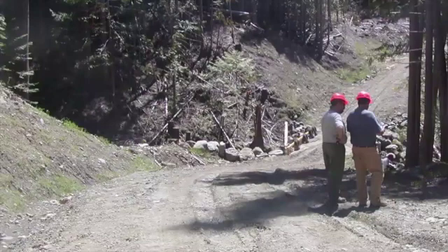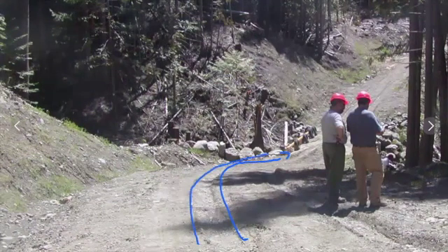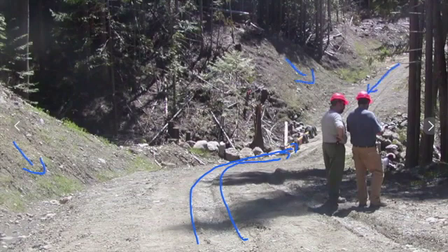If we conduct an assessment using a site like this, we will first ask where the water is going to run. In this case, it will run down these road ruts. Let me just show you. You'd see it would run down these ruts here, onto the bridge and then into the stream, and then maybe down these cut banks here, and down this. You can see all the rutting on this other road surface on the other side.